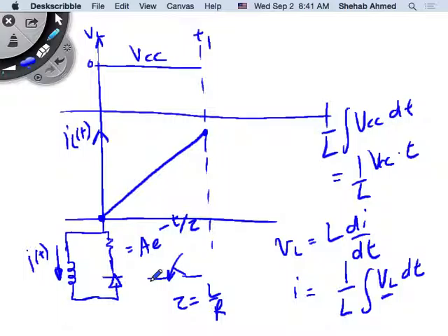But you need to understand that now I have a resistor in my circuit, not just an inductance. When it was an inductance, it was a pure straight ramp. When I'm discharging my inductor energy, it's exponential. You're going to be discharging through an exponential. That's all I wanted to say, basically. So this is the equation, A e to the minus T over tau, and you will solve a lot of circuits and problems and learn how to use this.